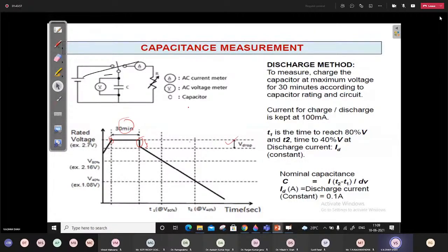So when I'm applying the charge, the initial part of your sheet will be connected with some source to charge your supercapacitor. Then definitely the part near the terminal will charge to a full level and it will immediately show that the capacitor got fully charged. But it is possible that the internal part of your supercapacitor may not get fully charged. That's why you have to keep it for a 30-minute rest so that the complete supercapacitor gets fully charged.